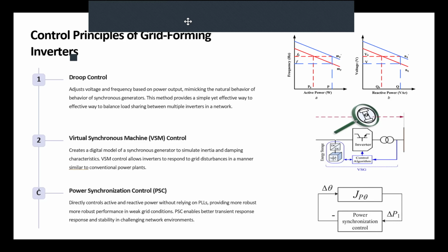But how about reactive power? We said reactive power is the amplitude of the voltage. Now, if we do grid forming, we dictate the voltage, the amplitude of the voltage at the terminal. That means we basically lose one of our leverages in the control system. Now we don't follow the voltage, the reactive power demand based on the level of the voltage. How could we deal with that?